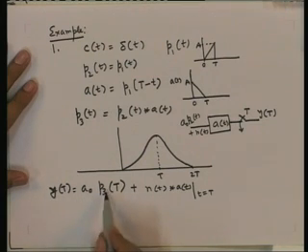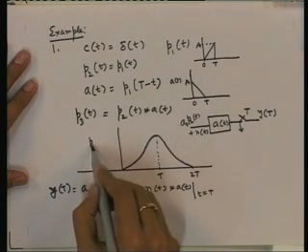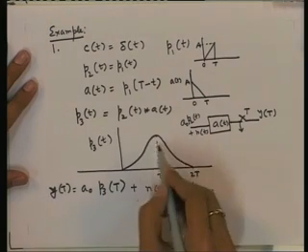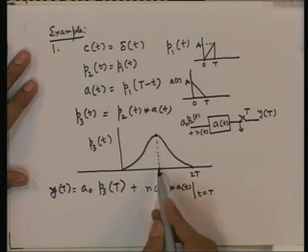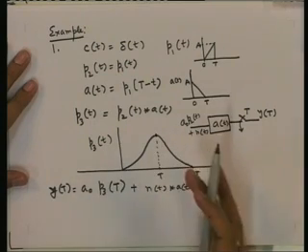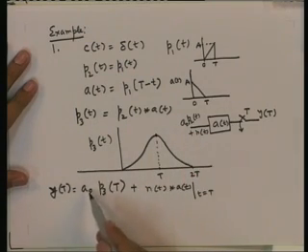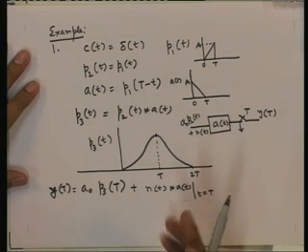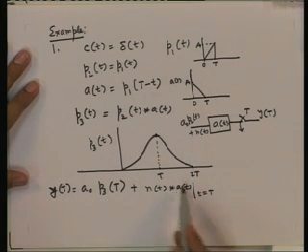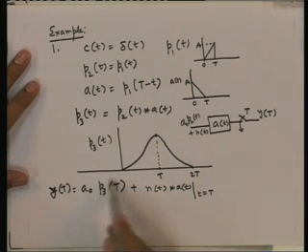But P3t is maximum at capital T, you can see here. So we want to amplify this A naught to the maximum, that is why we are sampling at capital T: when you sample at capital T, P3t gives the maximum value, and as a result this A naught value is scaled up to the maximum level possible, and this noise then becomes negligible compared to this.